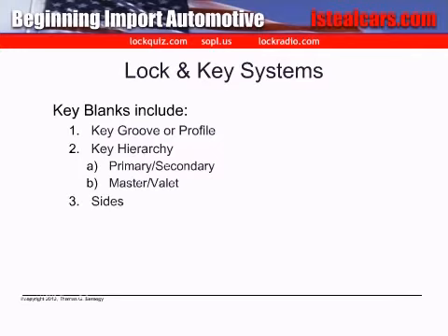The number of sides used by the key is also an important attribute of the key blank. While more cars are coming with high security and specially designed keys, the most common automotive keys are either single-sided or double-sided. For keys that are double-sided, they may also be either convenience keys or true double-sided keys. More on the double-sided keys is covered in the following slides. For now, let's take a more detailed look at the key blank hierarchy, that is, primary-secondary versus master-valet.